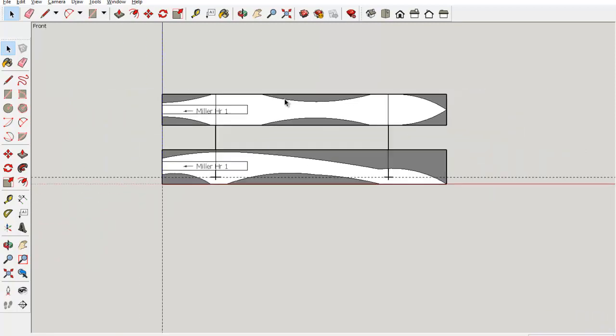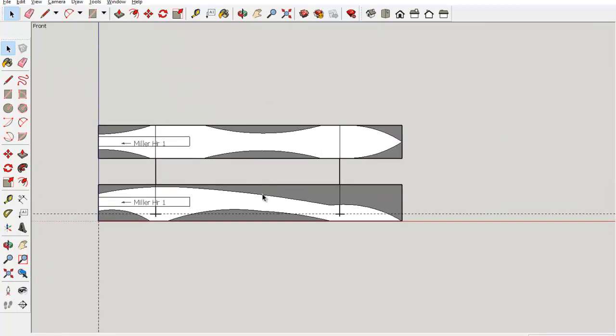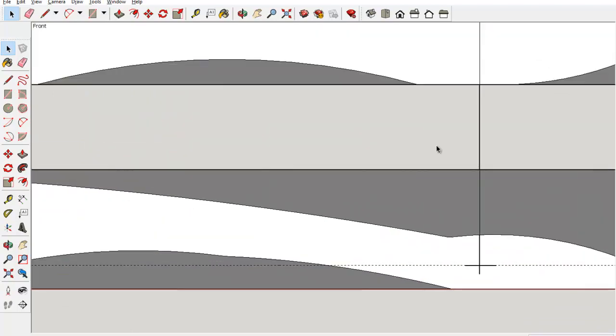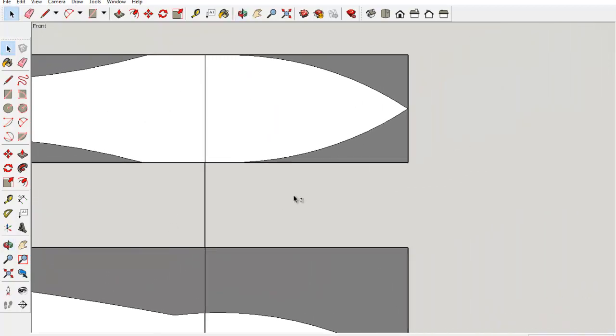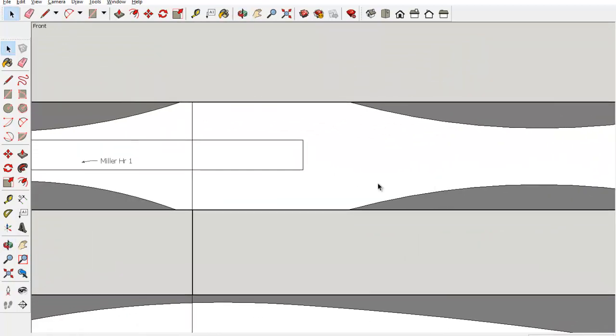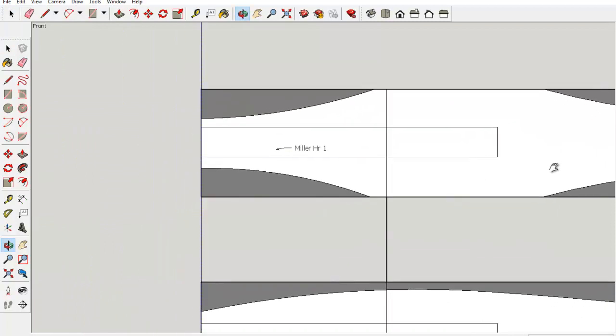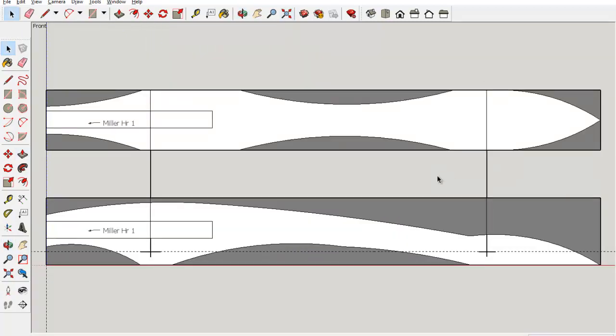There's one thing that I want to make sure we understand. The zoom in and zoom out, again, is the scroll of the mouse wheel. And then if I want to pan around, I hold down the Shift key, not Control but Shift. You can see that little plus minus sign comes up, and then I press the mouse wheel down, not the button, but the mouse wheel, and it turns into a little hand which pans this around. So again, hold down Shift, press the mouse wheel, and it pans it around, and we'll get back here to get to our kind of home look at that.